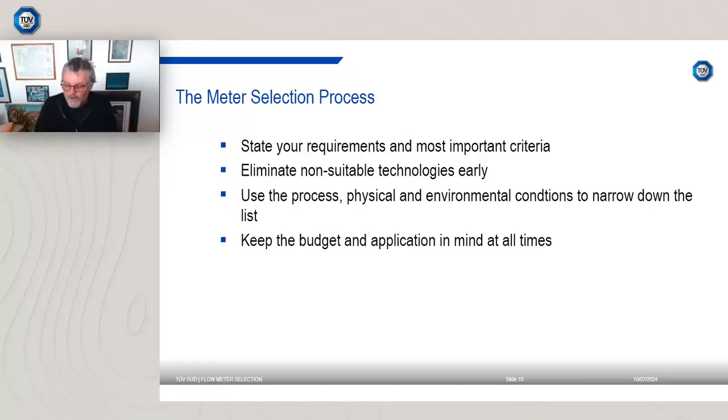If you have a custody transfer requirement of plus or minus 0.25% for liquid, well, that's very unlikely to be flexible. That's not going to be something that the commercial partners and the government regulators are going to let you away with. If you say, well, I couldn't spend that extra $50,000, so I'm going to give you 0.3%, not 0.25%, in my experience, that's unlikely to wash. You're not going to get away with that. So you just have to keep it in mind at all times.